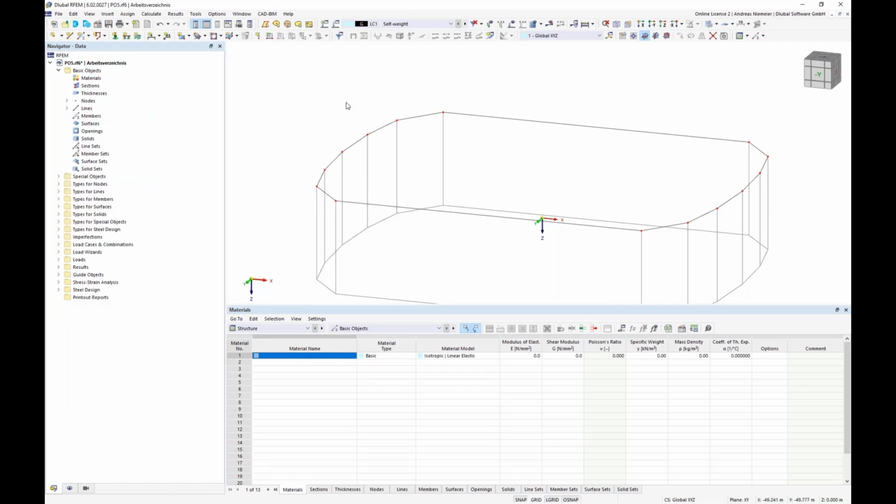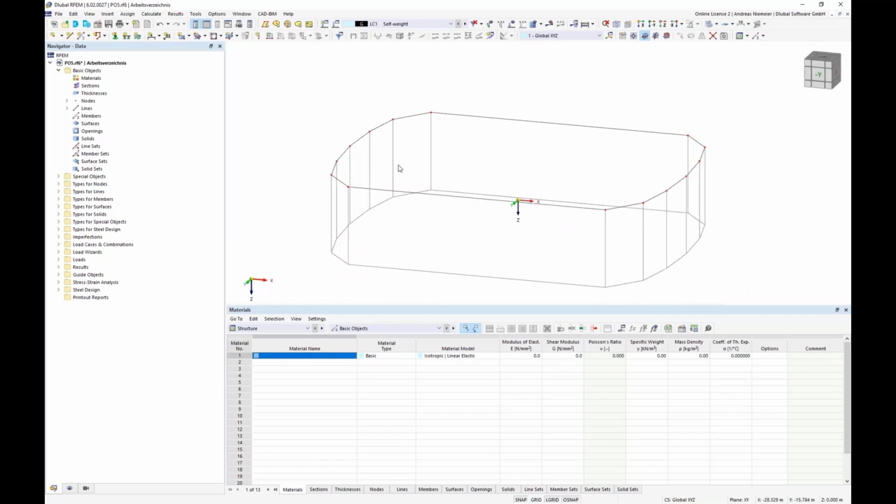Now let's take this geometry as the start condition, but as you also saw in the pictures, the roof is covering this building block a little bit. Therefore, we scale it up so that our roof really covers this block. Let's take some measurement, for example, 0.5 meter.